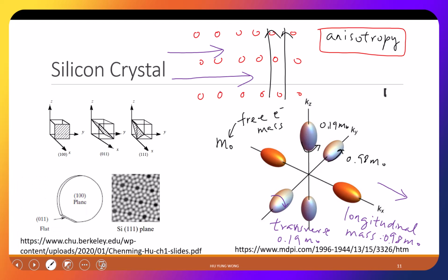And again, this is not difficult to understand. Think about me. If I go in front, I can travel very fast. But if you want me to walk sideways, I am slow. I am anisotropic also in this sense. If they ask me to go backward, even slower, right? But this is something you don't have in nature, front and back. So you agree electron has different mass. You have 6 valleys for silicon. You can reside in them, depending on which direction you're transporting. You get different mass. It can be as much as 5 times different. And their property is anisotropic.